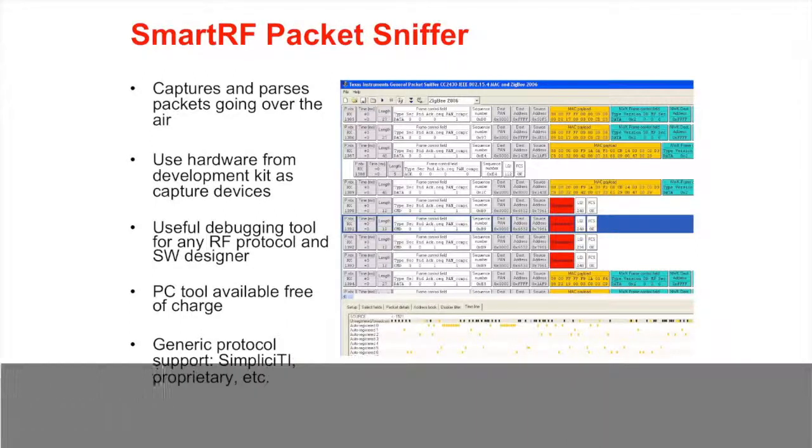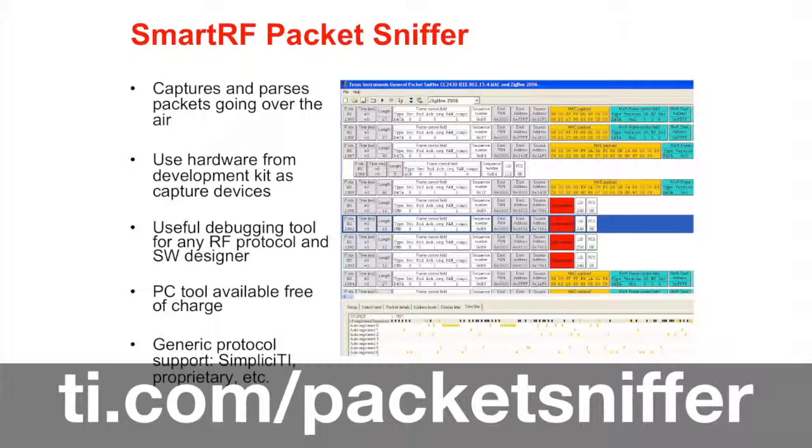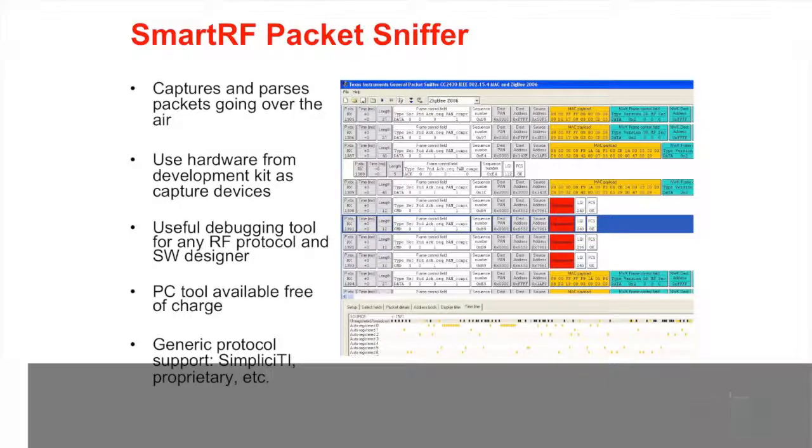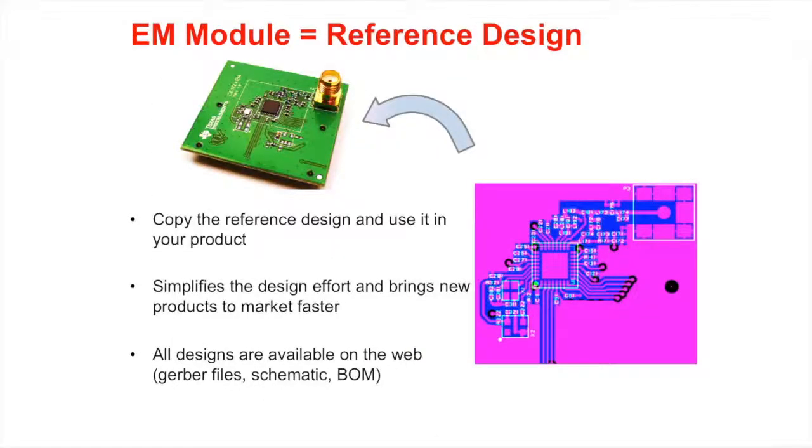The Sniffer's product page at ti.com/packetsniffer provides an overview of what capture devices are supported and what the capture devices can do. TI provides schematics and Gerber files for all products. Use the exact same values and placement of decoupling capacitors, balun, matching, and filter components.